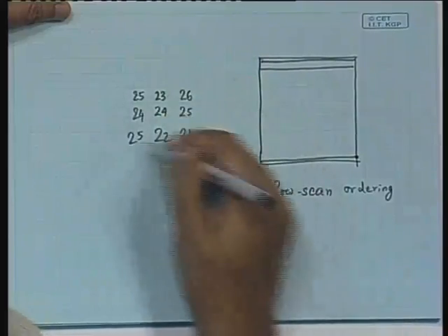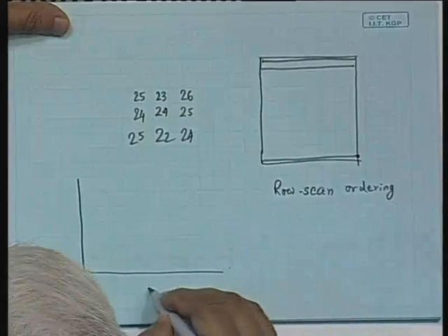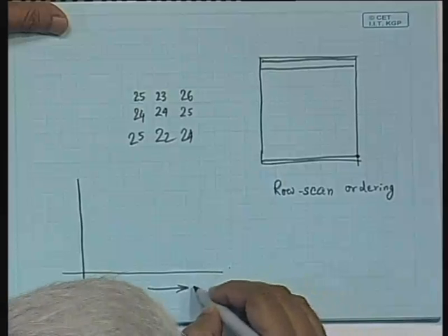So in terms of a frequency domain representation, we will be saying that there is only a small amount of variation. If we plot the energy of the signal versus the frequency, in this case the spatial frequency, we will find that a predominant amount of energy is there in the DC component itself, and some low frequency portions of the signal spectrum will also contain some energy, but the high frequency components will have very minimal energy. Not for this small example image, but for a general image, let us say this is where I plot the frequency.